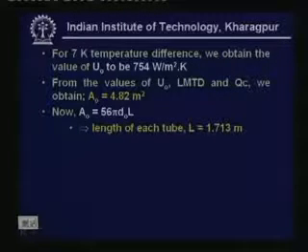Okay. So this is how you have to do the design of a shell and tube condenser. Of course, this is not a complete design, this is only a thermal design of shell and tube condensers. So you have to proceed in a systematic manner, first by getting the required properties, and then using the correct formula, and then calculate the various quantities, and then you have to go for trial and error method.